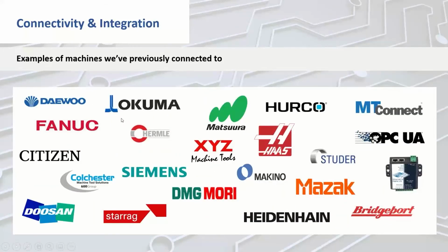And when we come to collecting data from resources, then here you can see a whole list of, typically these are NC or CNC machines that we connect to either using a network cable or via the small box, the photograph you see on the right there, to collect some digital I/O. So if it's an older legacy machine, it has no network capability, we can wire in and try and understand whether it's running, whether it's stopped, maybe whether it's got an alarm condition.